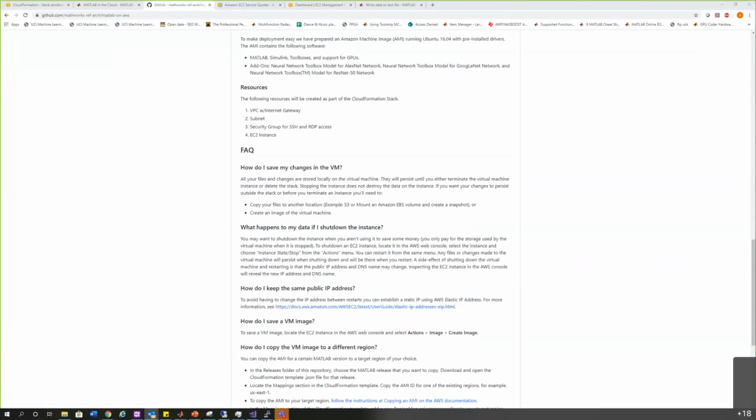Sometimes GPUs do compare with FPGAs, but the only problem with FPGAs is, with the kind of app I showed you, signal processing algorithms, it takes a little bit of work to realize that Simulink or MATLAB code, or even a DSP code for filters, and convert it to VHDL and then realize it on hardware like a Xilinx board. There are a couple of steps involved, and it requires some expertise in the area before you can start realizing your models in FPGA.